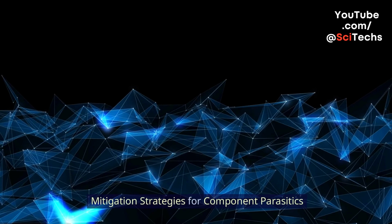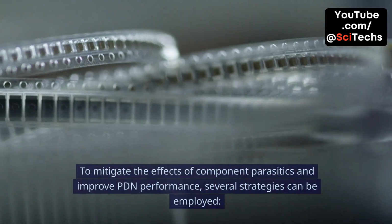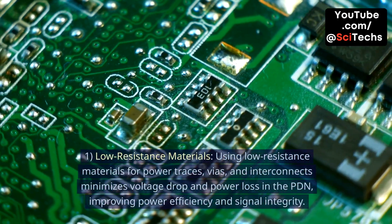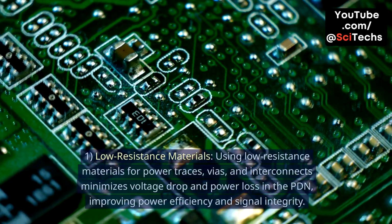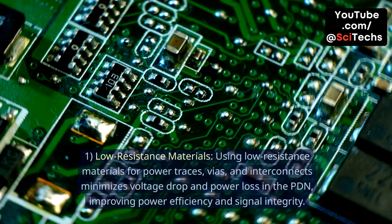Mitigation strategies for component parasitics. To mitigate the effects of component parasitics and improve PDN performance, several strategies can be employed. 1. Low-resistance materials. Using low-resistance materials for power traces, vias, and interconnects minimizes voltage drop and power loss in the PDN, improving power efficiency and signal integrity.